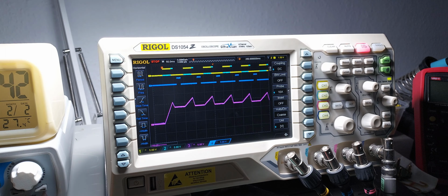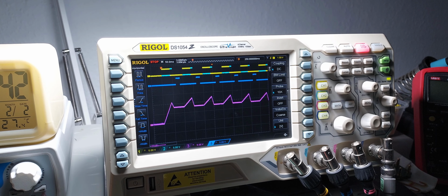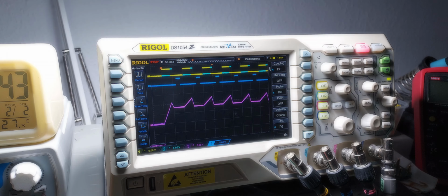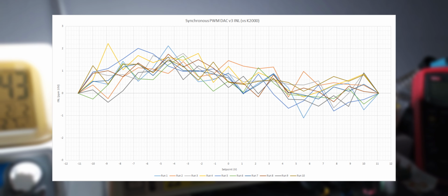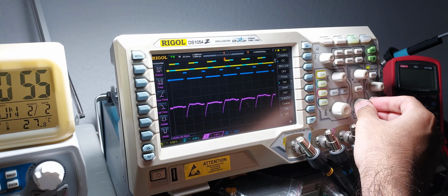The integrator is sampled during the blanking period to give the sample and hold circuit a stable voltage to work with, hopefully eliminating the output spikes. Although the linearity is greatly improved, with no quadratic effect that is a side effect of switching on the reference side, the spikes are still there, but with reduced amplitude.